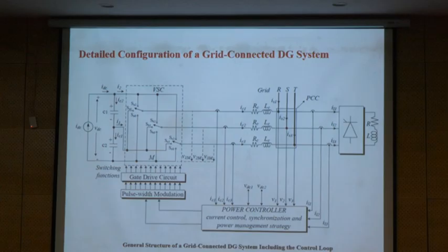I'm going to control it in a way to inject power from here to here. Okay? So what I need is where or what is the level of the voltage that I'm going to synchronize my converter with. So we need the information from the grid. So we get the voltage sample from the voltage for the analysis, for the control design.